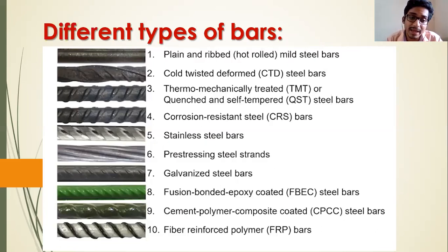In most cases, it has been seen that in prestressing steel strands, local corrosion happens more than normal corrosion. Local corrosion means a particular region, a particular point, a pit hole. It will have a pit hole and it will damage the strands. And if it damages these strands at one particular point, they will not be able to take the whole load, or provide enough bond or the anchoring that has been designed for that particular assembly.